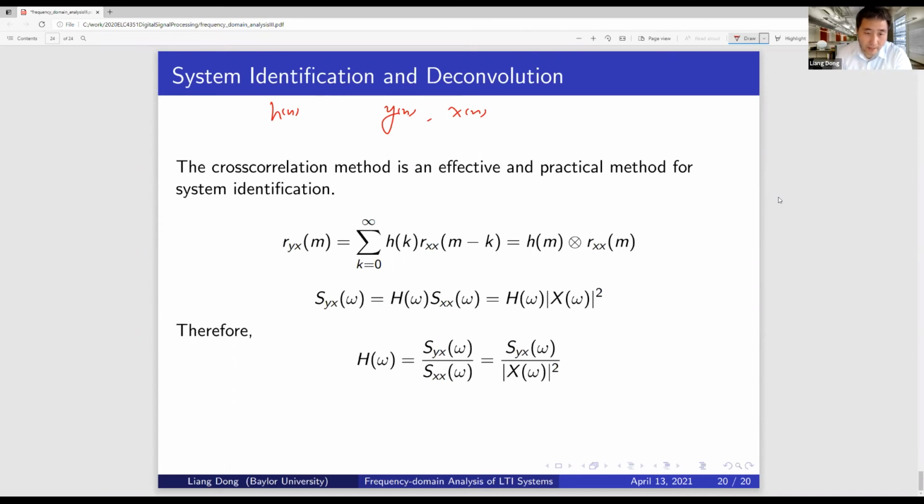The other problem is that those signals X and Y, these observations, will change. Signals change as a function of time, so x[n] will change, y[n] will change. To identify the system, you can only take a finite window of the signals x[n], y[n], then do the deconvolution to find h[n].